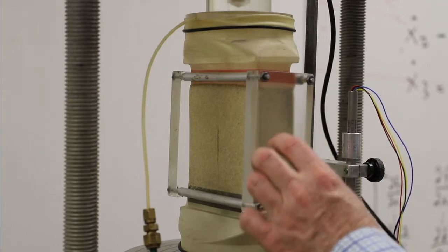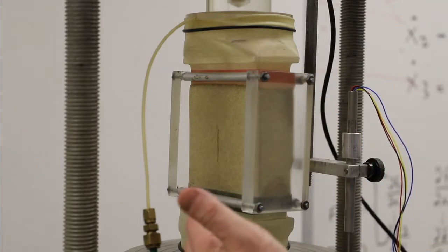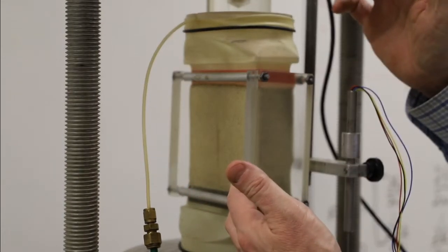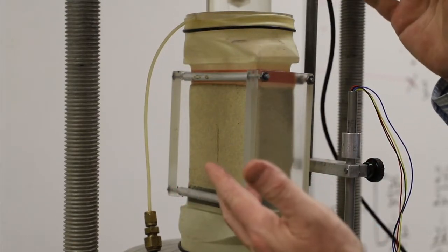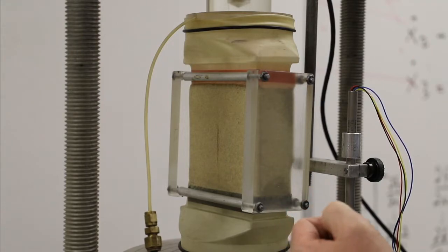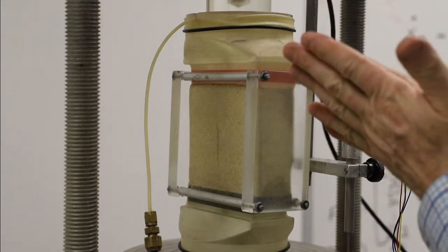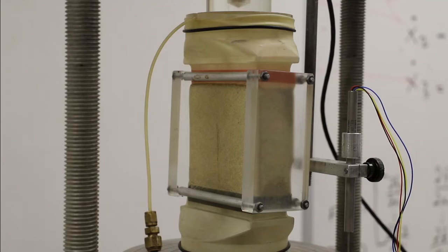So we have essentially almost a rigid block to the lower left and a rigid block to the upper right, where there isn't any further volume change happening, and all the action and all the shear and all the volumetric strain is happening across that narrow zone, that localized failure plane.